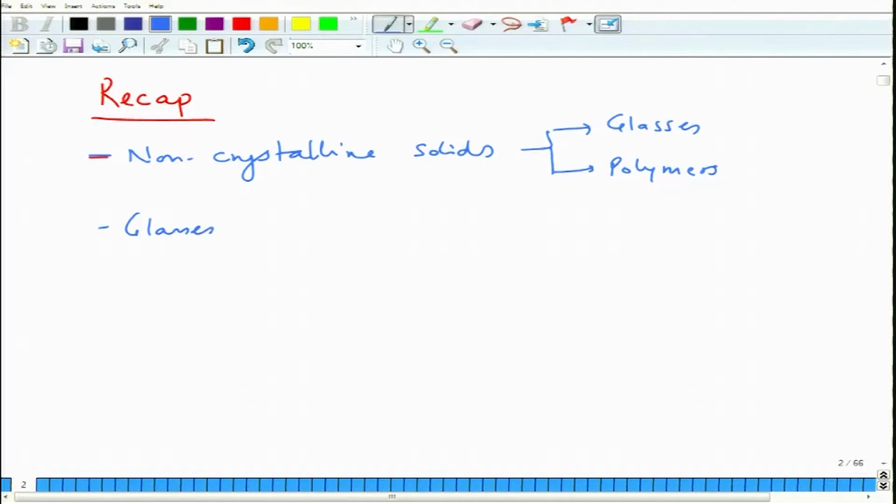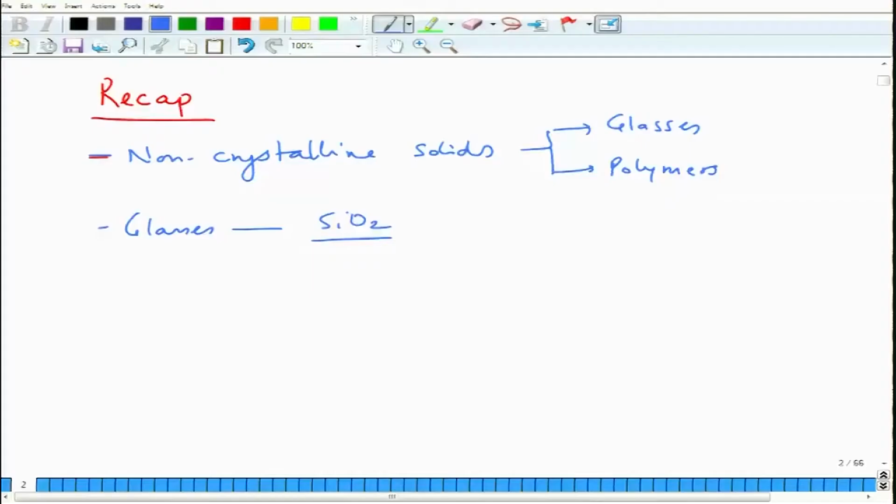Glasses are mainly based on SiO2 units, and the silicon is basically tetrahedrally coordinated. So it depends upon the sharing of oxygen atoms between tetrahedra what kind of structures silicon oxide can give rise to. So there are plenty of structures that we looked at in the last lecture, depending on the coordination of oxygen atom. It can make a completely 3D crystalline structure as well, which is in the form of quartz, if all the tetrahedra were beautifully arranged in a hexagonal fashion.